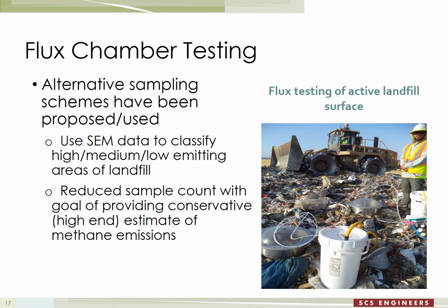There have been some alternatives where they've used surface emissions monitoring as a screening tool to determine the different areas of the landfill, and particularly to identify any hotspots that you want to make sure you don't miss, and then reducing the total number of chamber locations using the pre-screening data. Again, even though this method has been used in some regulatory and non-regulatory environments, it doesn't have any formal regulatory approval for its use on landfills.